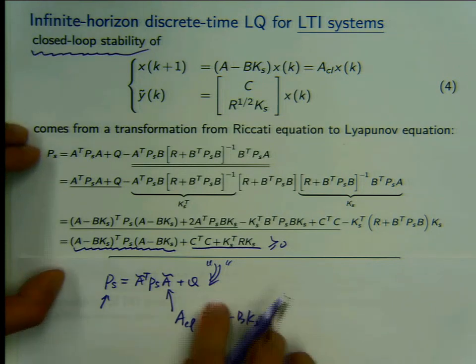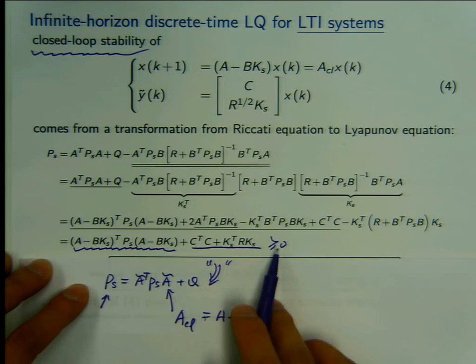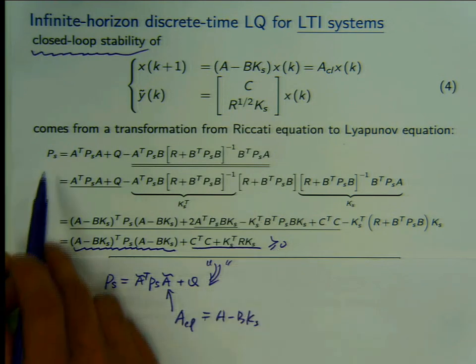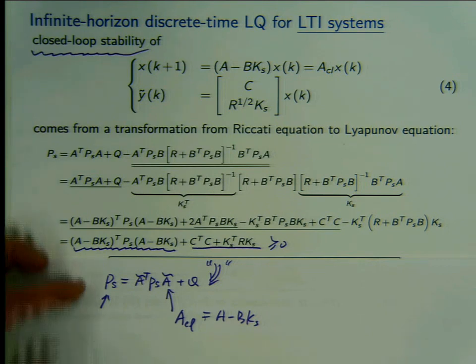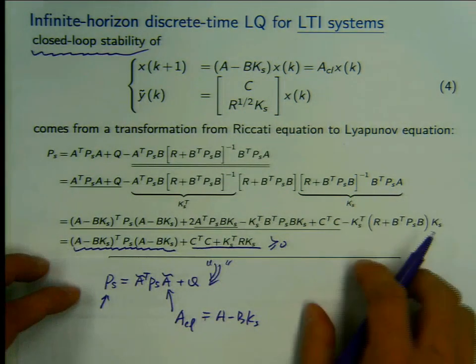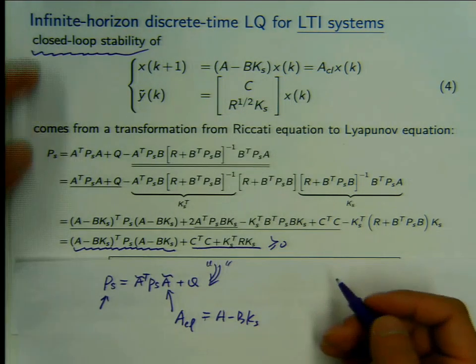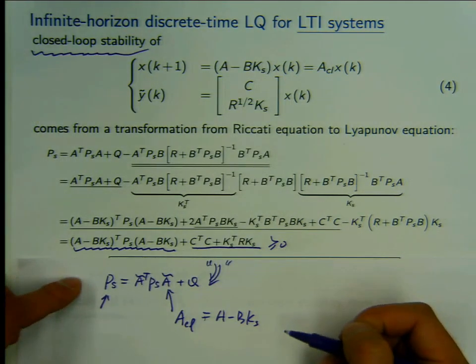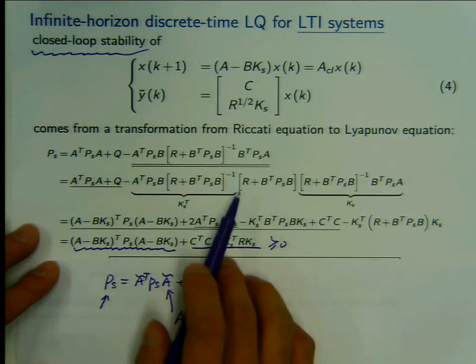So in this Lyapunov equation, we have found something that's positive semi-definite, and this is positive definite. That means the system is at least stable in the sense of Lyapunov. After a few more algebra steps, the system turns out to be even asymptotically stable. But that's the big picture, and the details you can read back in the notes.